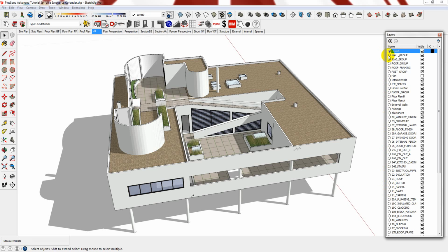Whatever layer the dot belongs to is the actual layer that you're going to draw it on. So for example, if you had set up a CAD line layer and you assign it on that layer with the dot, that means if you draw new lines, they're actually automatically going to be assigned to that layer. I always set mine to be defaulted to layer 0, and that way I can change it thereafter. And it will be more easily trackable if you do it this way.